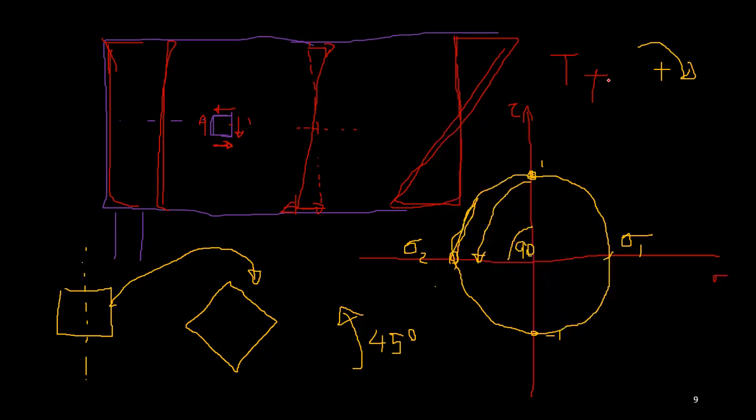Our sign convention is tension positive. It is in compression, and if you go to the other surface, it is 90 degrees, so that means 180 degrees on the Mohr circle. It is sigma 1, and this radius is 1, right? So this radius also 1. So this is also 1 megapascal, and this sigma 1 is positive. So that means it's a tension.